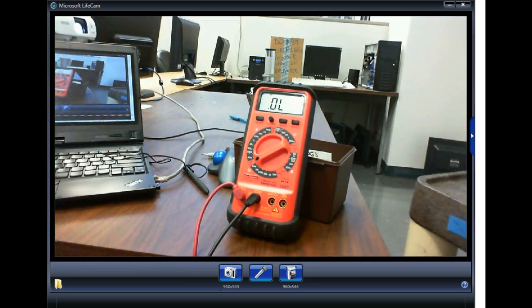So basically, it doesn't make any difference how big the device is. If it's silicon, you're going to be able to do it. Now this measures 7/10 of a volt, this is not germanium, this is silicon. But the problem is, it's heavily doped, so it means it's got a lot of silicon in there. It's got a lot of majority carriers because this guy here is rated, I think, about 60 amps.